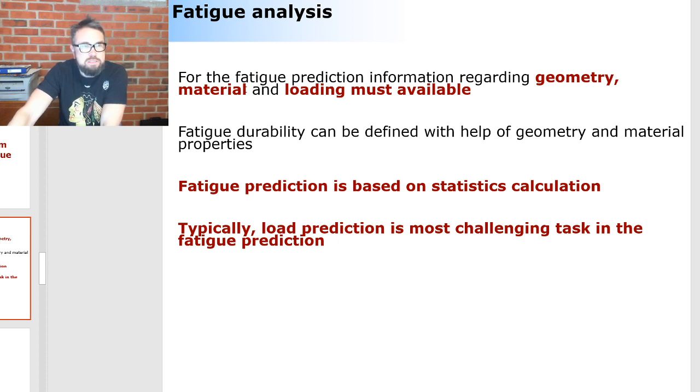Material for sure is well known, but the big question mark is typically how the loading is imposed on the structure. Because if we're dealing with a structure that does not yet exist, it's very, very difficult to get the loading history. The only real way to get a loading history is by using multibody simulation. And that's why these two subject matters come together: fatigue and multibody dynamics.